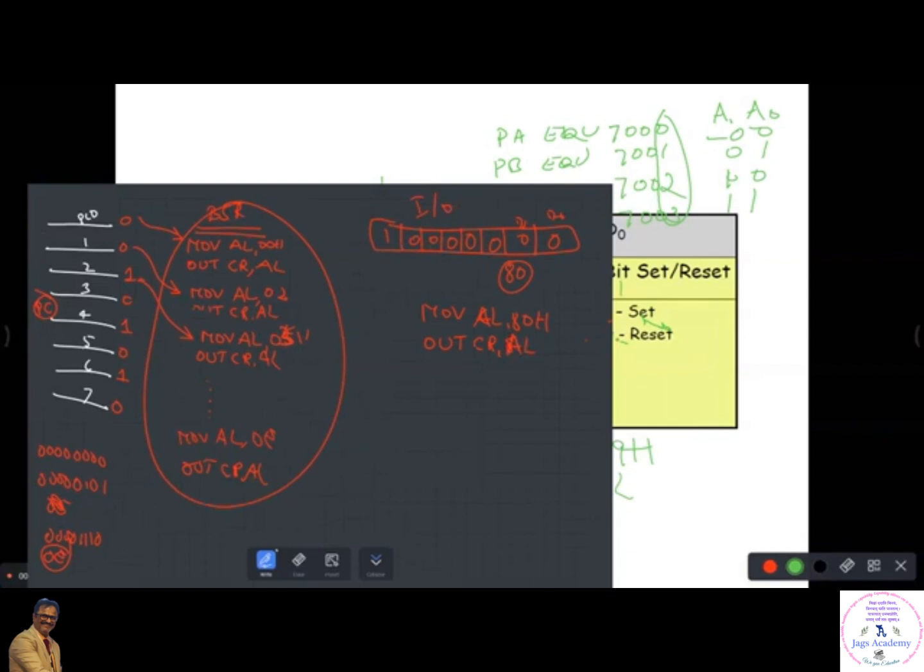What will these two statements do? This will set your 8255 in the output mode, where port C is configured as output. This is done only once. Now you have to put this data into port C. You just have to put the entire byte.